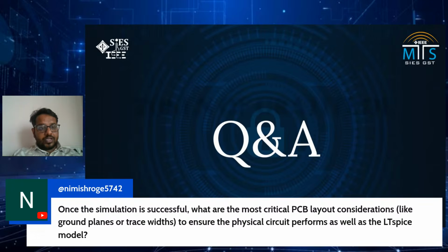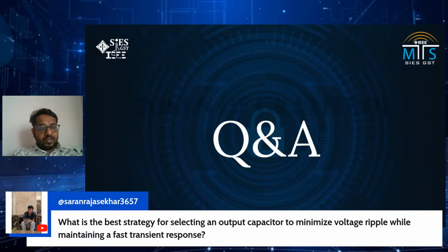We also try to keep some filtering capacitors near the MOSFETs, like there will be high frequency filtering capacitors, there will be low frequency filtering capacitors, and always on the second plane there will be a ground plane, which will act like a shielding, which will try to absorb the noise. So there are many PCB guidelines which we have to follow while designing the SMPS circuitry.